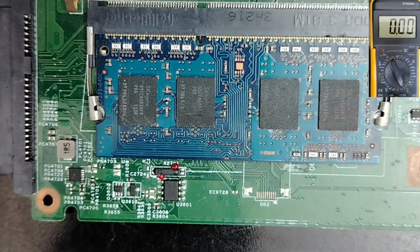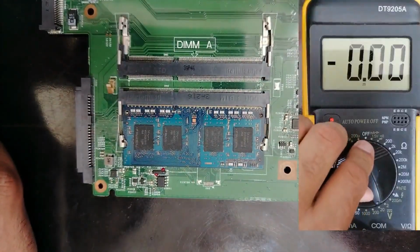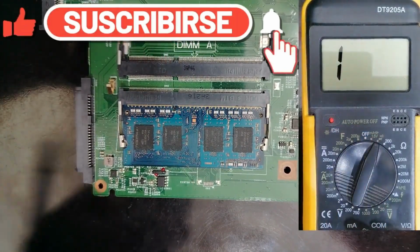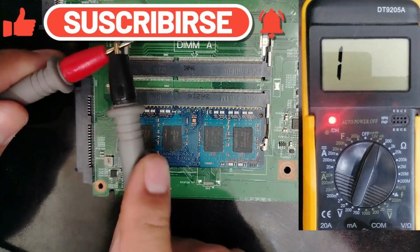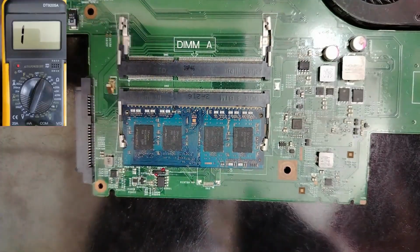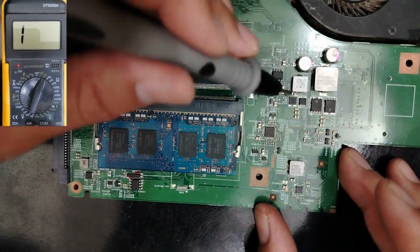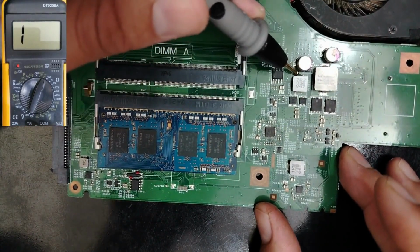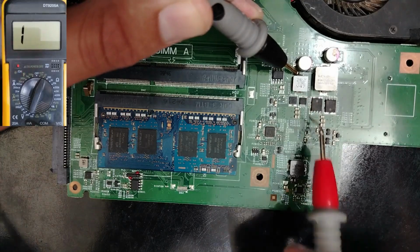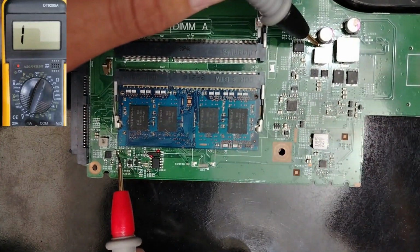Okay, guys, let's zoom out a little bit. Good. Okay, let's put the multimeter again to the continuity option over here. Okay, guys. So let's check. Good. Continuity option seated correctly. So, guys, if I put one probe in this inductor, in the 3.3 volt inductor, let's put it here, for example, because it's the same thing. Okay, so one probe in the 3.3 volt inductor, and let's go directly to this capacitor.